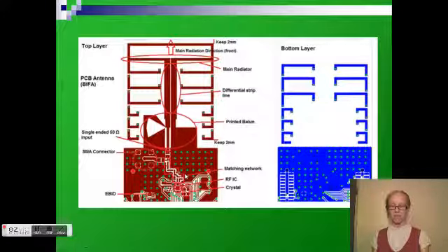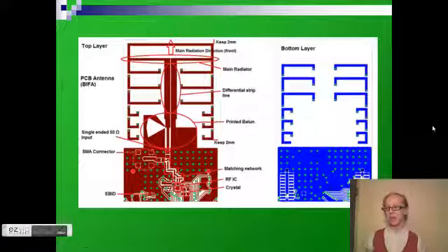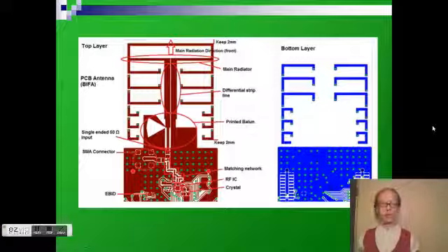Now, the matching network matches impedances in order to ensure maximum power transfer. Maximum power transfer both maximizes efficiency and protects the circuit. If impedances are not matched, the circuit will see a reflected wave, which will build standing waves on the transmission line between the source and the load.